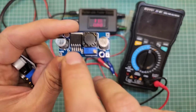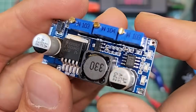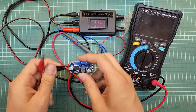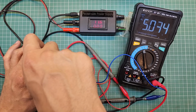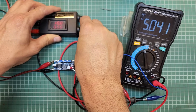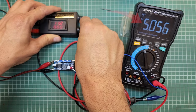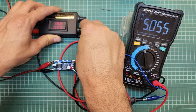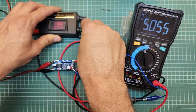Note that this was the XL6009, which was a boost regulator, but this is the LM2596, which is a buck regulator. Look here, when I change the input voltage, the output voltage stays fixed, which was predictable and absolutely normal for this module. But the interesting point is in the output voltage. Here, I should be able to see those fluctuations in the oscilloscope.